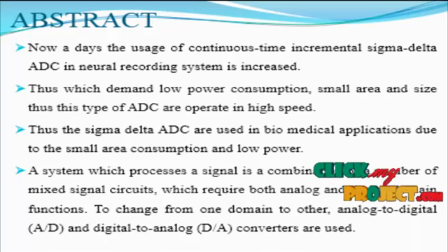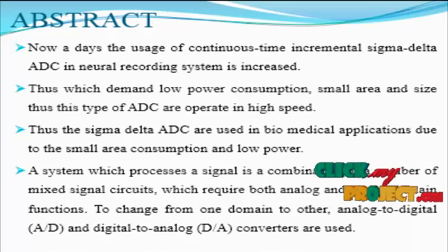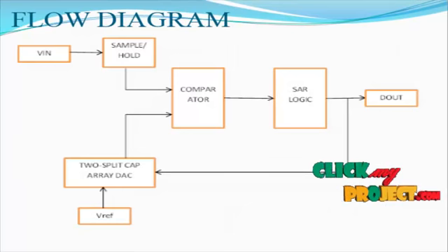From the survey, it can be noticed that most of the power efficient designs with these specifications are composed of flash or SAR ADC combined with time interleaving. The SAR ADC is a well-known energy efficient architecture, while the speed of SAR ADCs can be further improved with comparator interleaving, asynchronous control loop or multiple bits per cycle. A flash ADC is known as the fastest ADC architecture, but power hungry. By adopting interpolation or calibration, outstanding energy efficiency can also be accomplished under advanced technology nodes.